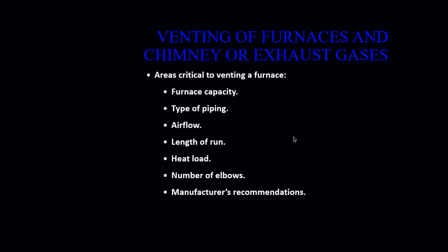Your areas that are critical in venting a lot of your furnaces and equipment are the furnace capacity, the type of piping that's being used, airflow, the blower itself, the length of run, how far away the furnace needs to heat, your heat load, depending on how cold it is outside and inside, and the number of turns or elbows in the ductwork or in the flue pipe itself is going to play a critical part in how well a furnace actually ventilates.